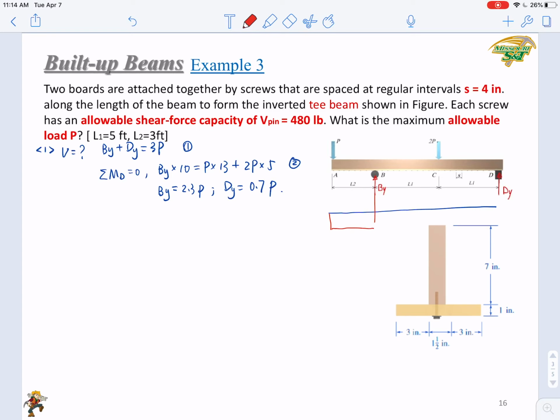You will raise it to 1.3P. Then to point C is minus 2P, you get a negative 0.7P to the end. So here you get negative P, 1.3P, and negative 0.7P.